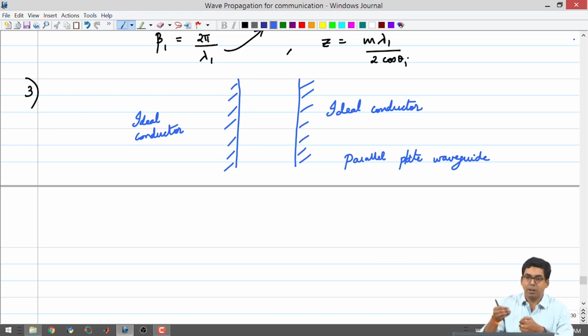The consequence is that you are going to have propagation that is slower than in a homogeneous dielectric medium, because it does not follow the path of the least distance between point A and point B. It is bouncing multiple times and reaching the other side. So, you can call these kinds of configurations delays. You are taking a signal and passing it through this configuration at a specific angle. It will be delayed by so much time when it reaches the other side. So, in a simple scenario, a waveguide can be used as a delay element.